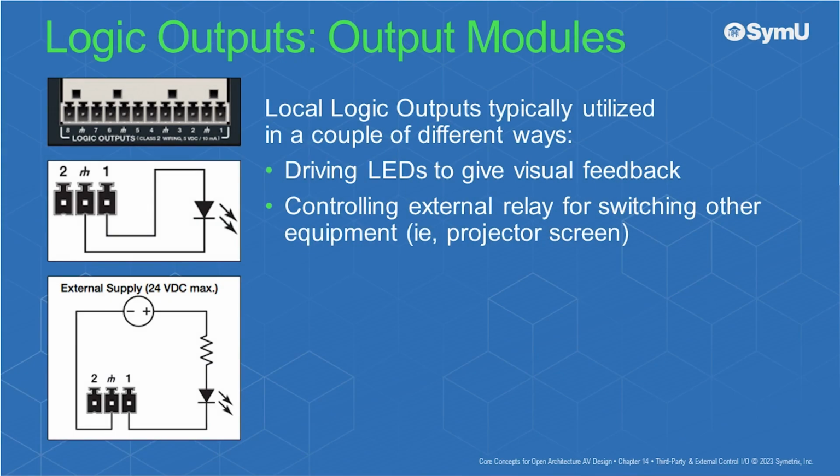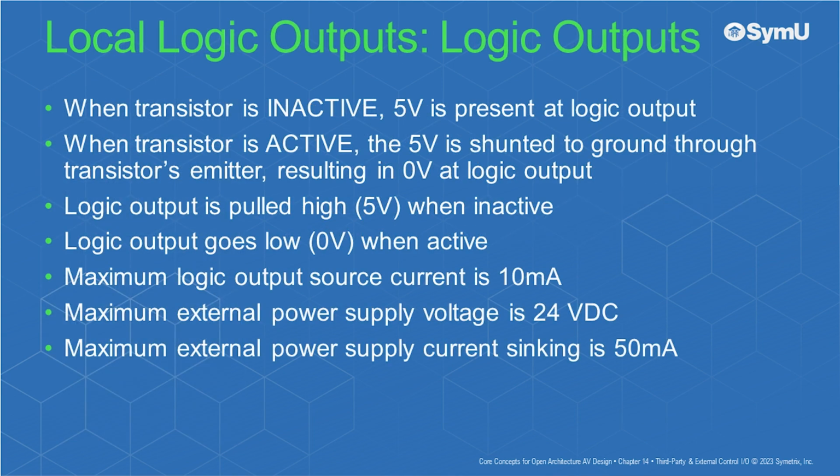Typically, local logic outputs are utilized in a couple of different ways, driving LEDs in order to give visual feedback to an end user, or controlling an external relay for switching other equipment such as a projector screen, or rack of other equipment. This is a very important concept.